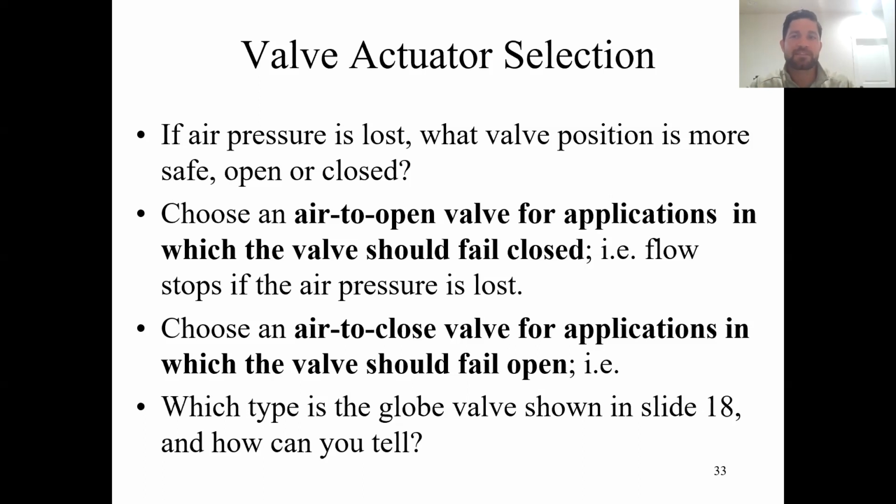Okay, so now that makes this next question easiest. What are systems that you want to fail open? Cooling water? Cooling water, right. So for a cooling water valve, you'd want to design it to be air to close. Hopefully these are a little bit obvious. Some things are less obvious, and it depends on whether something is going into your system or coming out of your system, and then you can decide a little bit that way.